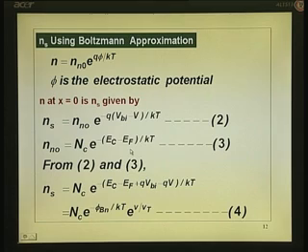Very simple actually, and once you have written this equation, if you accept that, in fact, because it is Boltzmann's law which we have used, the carrier concentration between 2 points can be related by the ratio of the carrier concentration being e to the power of phi by kT. That is what I used. So, the ratio of the carrier concentration here and at the bulk is equal to e to the power of that. You have to use the sign properly. As you go towards the negative potential, the electron concentration is low. So, that tells you that there should be minus. Even if you do not understand more than that, that is clear enough.